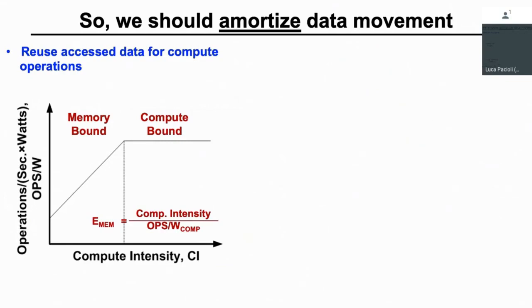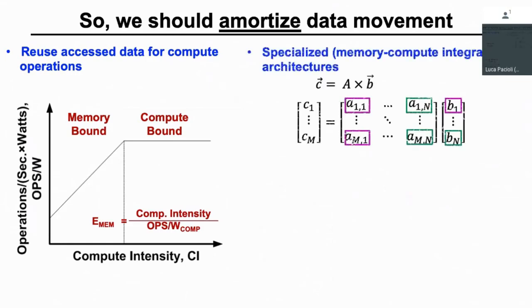And so you're limited by your compute. Otherwise, the more compute you can do, the better your amortization is, but you're in this memory bound regime. OK, so now if you're going to build a hardware accelerator where you know very well what the memory accessing patterns are and what the reuse opportunities are, you can now really take advantage of this to try and optimize around this amortization. And so let's just come back to this kernel, which I suggested is going to be important,